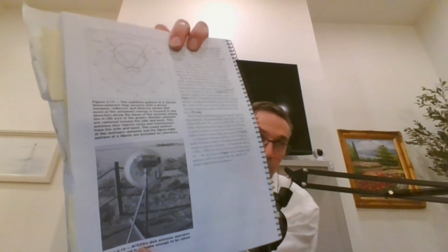Yagi was named for the inventor, so that's a common term a lot of hams will use, a Yagi antenna. Then you have this dish on 414, which is like a satellite dish type of thing. For UHF, it's a small wave, so that's a really small amount of space you're trying to collect from, so it becomes harder to receive. But if you aim it with a dish, you can go a long way. This is a 10 gigahertz example, really high frequency. For example, cell phone towers use the UHF band, so they're high frequencies and very directed. They don't propagate very far across the horizon, though.